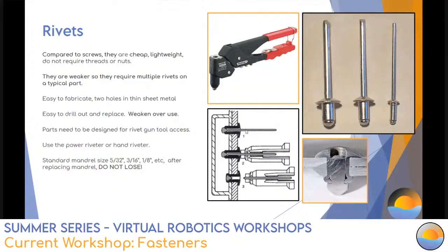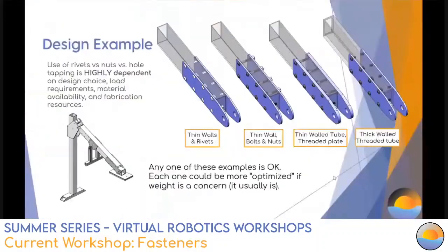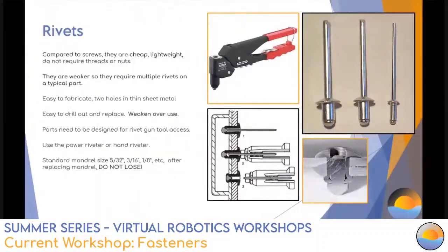Because how it works is you have this stem here, and you push the rivet through the hole, through both holes, and then you take the tool, and right here, it's going to pull on this stem and actually pull away on the material here and deform this whole area so that it makes it larger than the hole from the blind side. That's why they call it blind rivets. And then at the point that it's fully deformed, it'll pop off. And that's, again, pop rivet.